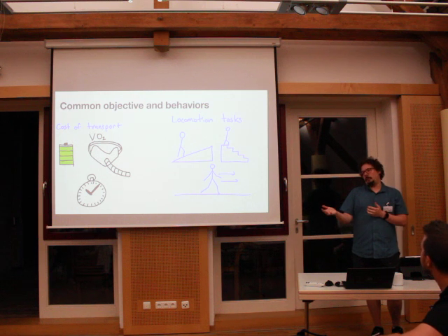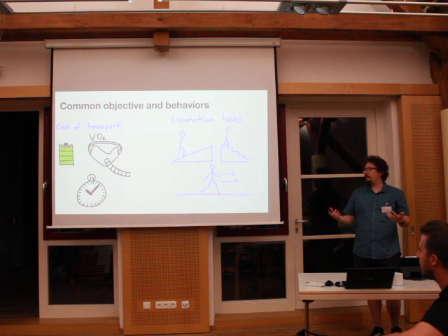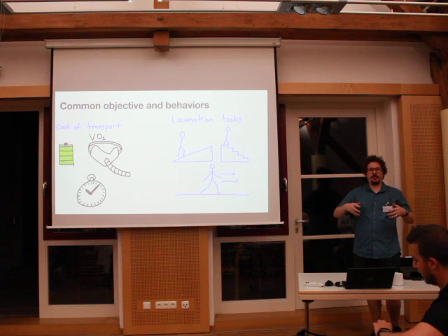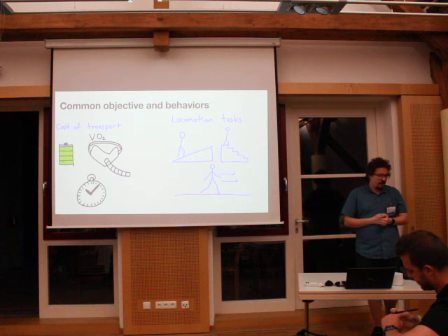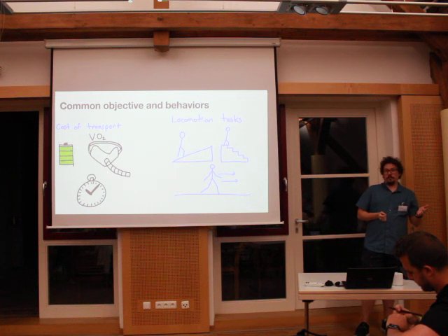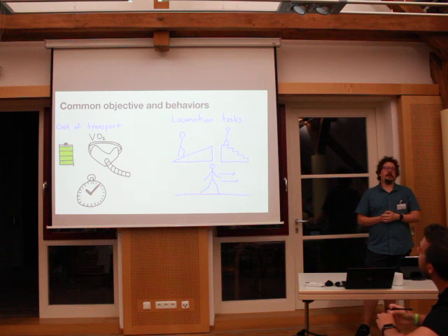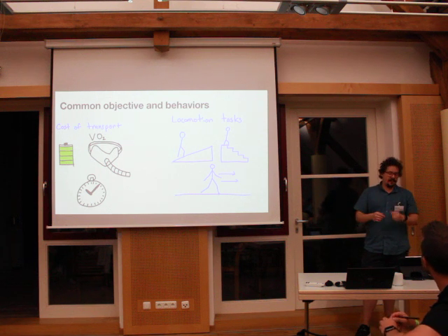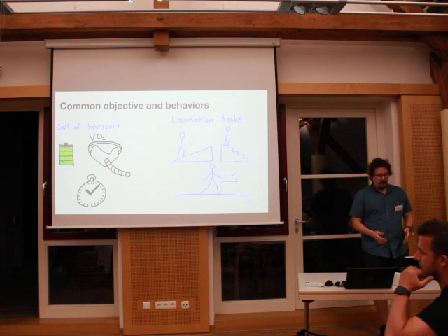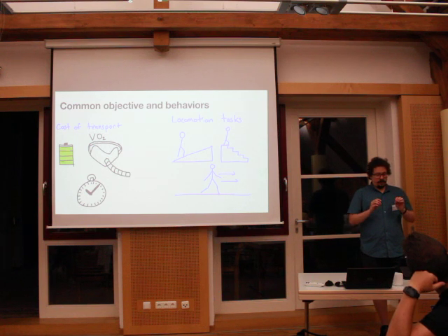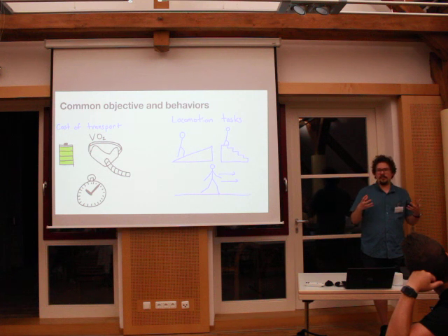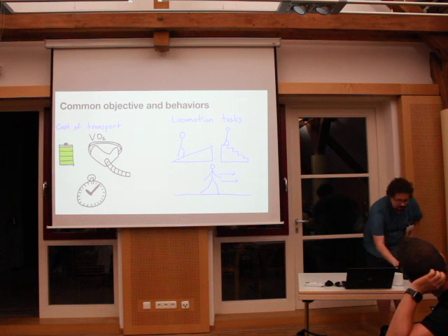You know, how long can my robot run on a battery? How much metabolic energy is a person expending when they use this device? Those things are going to determine their endurance, their power autonomy, how long they're able to operate. And also, there are many different locomotion behaviors that are considered in the dynamic walking community. So just for bipeds, you have walking, running, ramp ascent, descent, stair climbing, etc. So even within these different locomotion tasks, when we're designing a system, we could try to induce a multi-objective optimization problem that balances the trade-offs between these different behaviors.